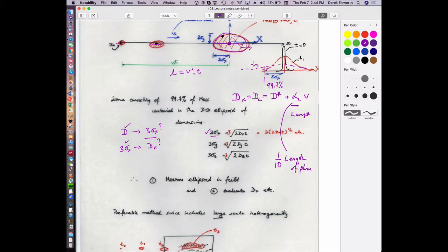So in other words, if this is the plume, then this is the length of the plume, and it turns out that the value of alpha that comes from that is returned, that is a given value. It would be equal to L over 10. Maybe I should call that uppercase L. So alpha is equal to L over 10, which is what we've just said here. And so 100 days later, the plume's going to be bigger, so alpha L will be bigger as well. So it's not a constant feature of the aquifer at all, it's a function of its scale.